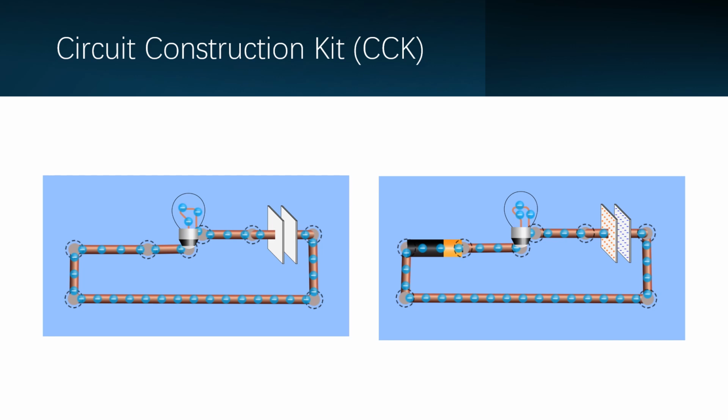The charging and the discharging times of the capacitors are then measured. For each resistor, the discharge time is almost equal to the capacitor charging time between the two capacitors, while for the 20 ohm resistor, the charge and discharge times are almost twice as long as for the 10 ohm resistors.